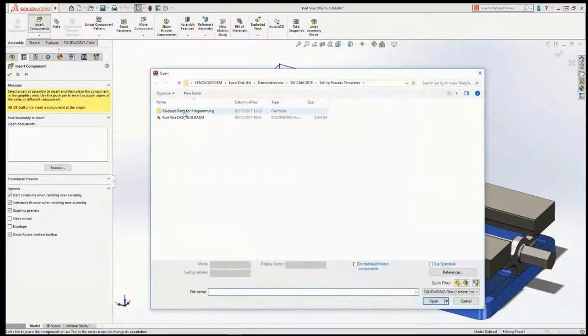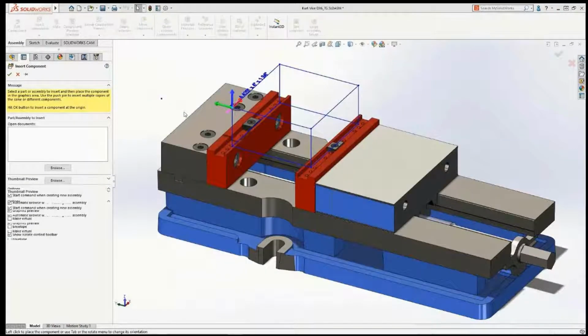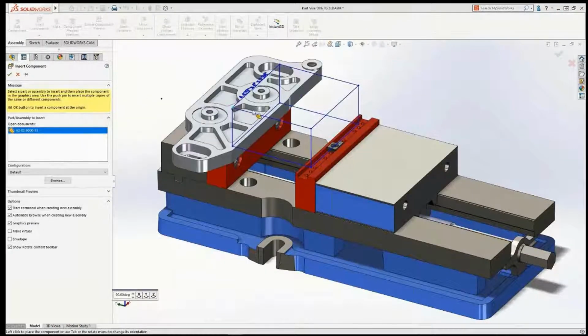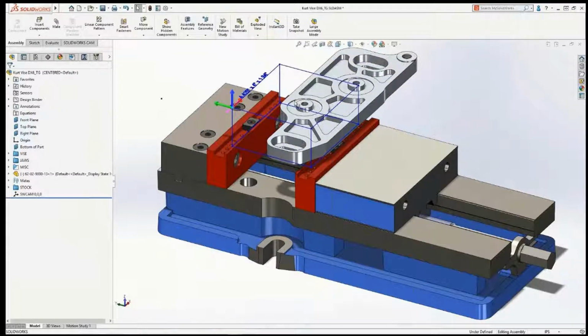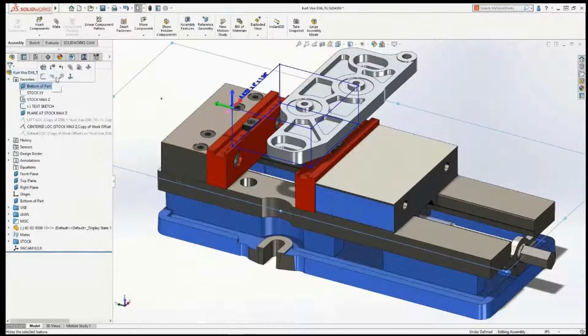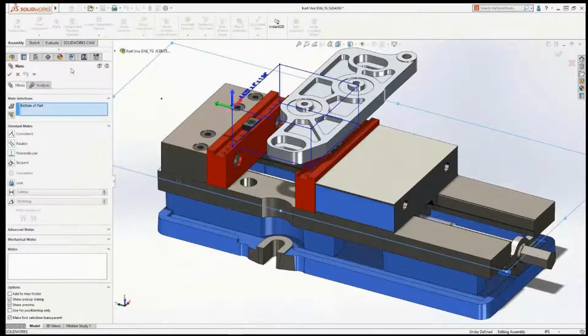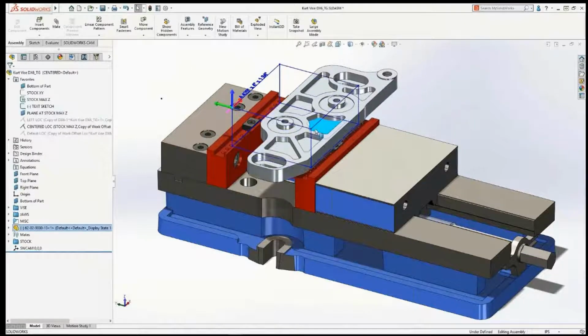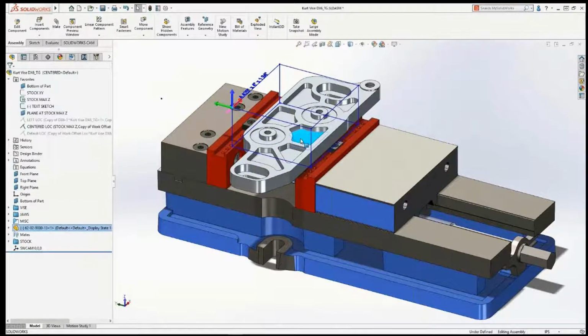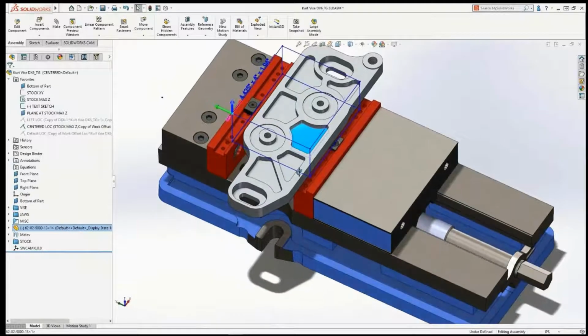Now let's start and insert our product. I will go and insert my brackets. It's a mounting bracket. And go with the interface of SolidWorks and do some mates to that bracket, so we can put the machining part in the orientation that we need to machine on it. So it's a normal SolidWorks procedure to mate that component.